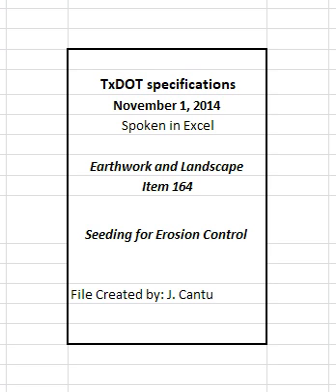3.4 Drill seeding. Plant seed or seed mixture uniformly over the area shown on the plans at a depth of 1/4 to 1/3 inches using a pasture or rangeland type drill unless otherwise directed. Plant seed along the contour of the slopes. 3.5 Straw or hay mulching. Apply straw or hay mulch uniformly over the area as shown on the plans. Apply straw mulch at 2 to 2.5 tons per acre. Apply hay mulch at 1.5 to 2 tons per acre. Use a tacking method over the mulched area.